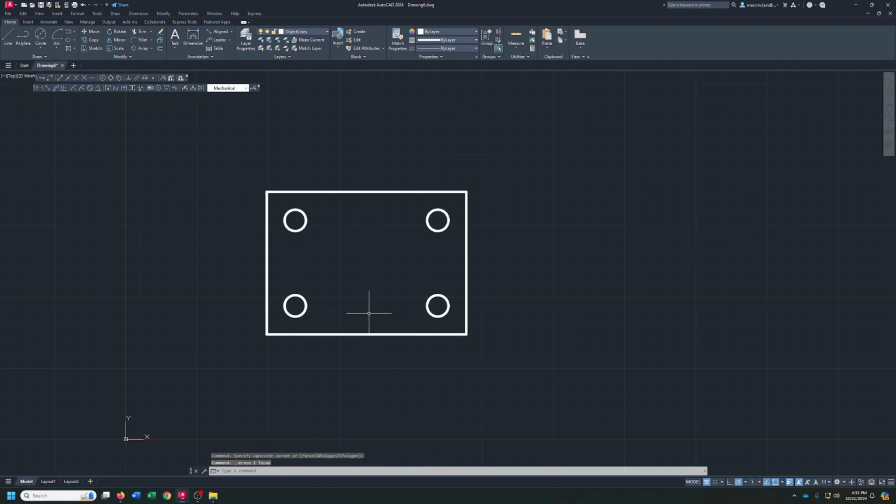All right, so now we're going to get a little thing in the middle, that angled V block. So we got that V block that we got to put in there. Now, if you'll notice, it does tell us that it comes down 0.25 and goes over 1.55. And we're going to go at a 45-degree angle. So let's go ahead and change this 45. All right, so there's my side, and this thing is 2.75 by 2.75.